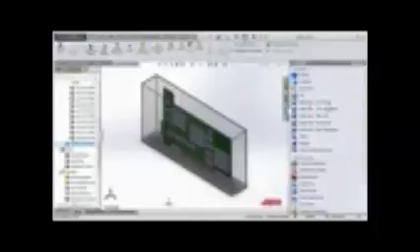We are going to add a heatsink. We will double-click on Heatsink Circ Inline. You can confirm the name in the component tree. Observe the default heatsink and double-click on the heatsink in the tree to access its property page. This will allow us to set up our heatsink.